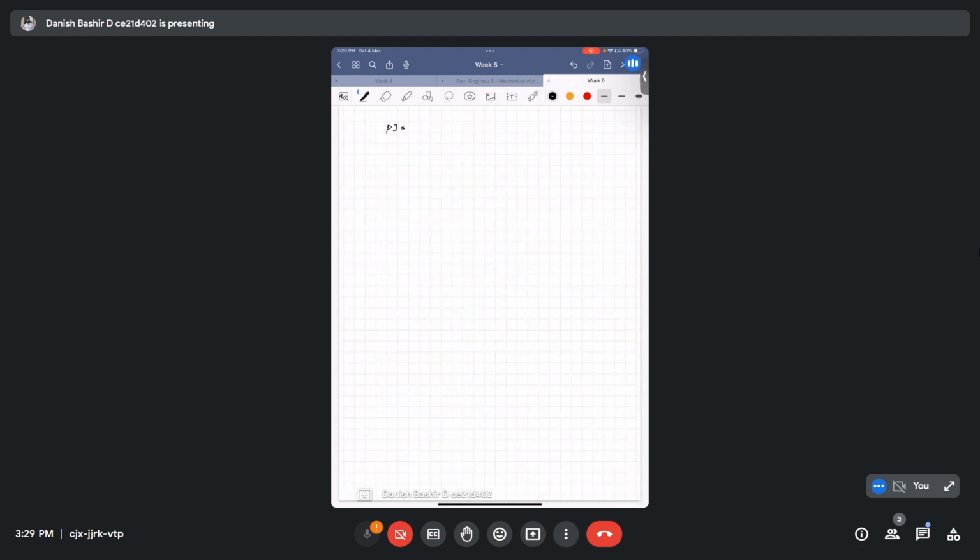When we take the inverse, it will be 1 plus d square by p square whole power minus 1 times x static naught. When you expand this, this will be 1 minus d square by p square, if I'm correct, plus some higher terms of d square by p square, times x static naught.